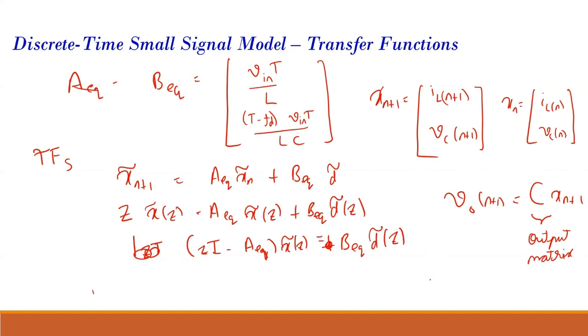So where does the one come from, sir? Yes. In the buck converter, you have a capacitor like this, and you have a resistor, and your inductor like this. This is my output voltage. So my output voltage is actually equal to VC in this scenario, because there is no ESR of the capacitor.